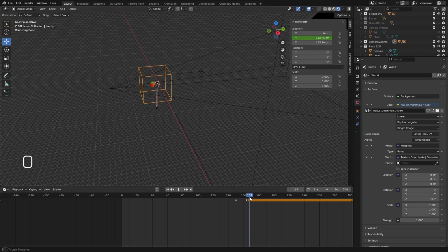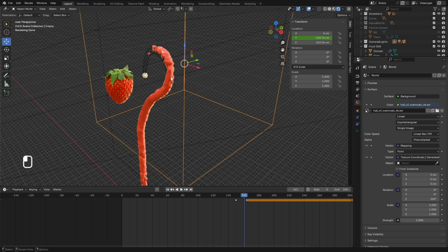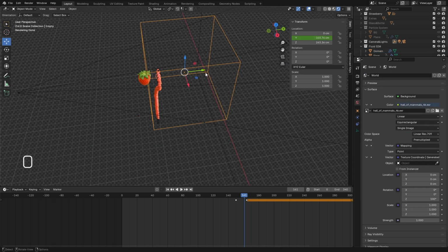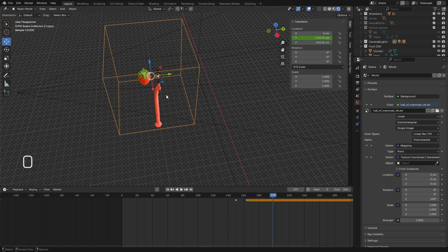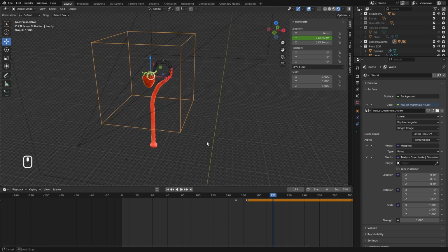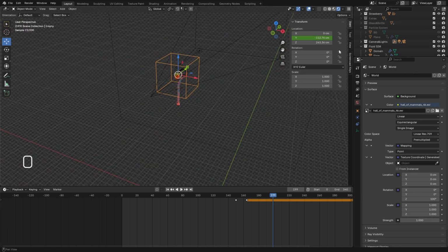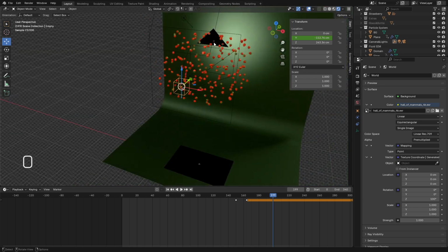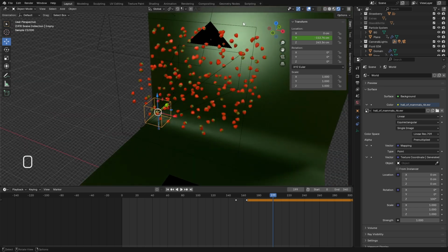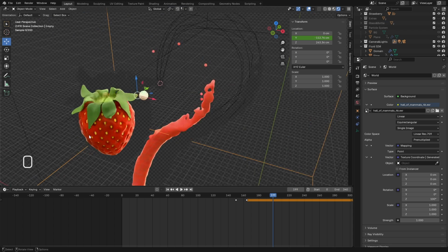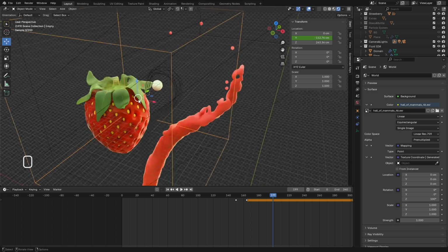When the time comes to render this one, I'm going to move this empty right here on frame 0 without any keyframe. So I'm going to render the background, the particle system right here, separately with the background right there. And then I'm going to render the hero alone.